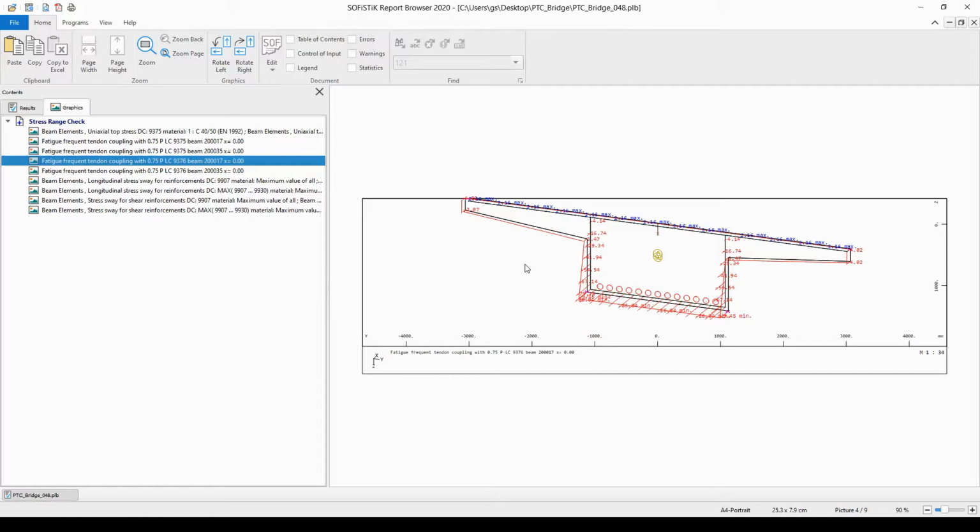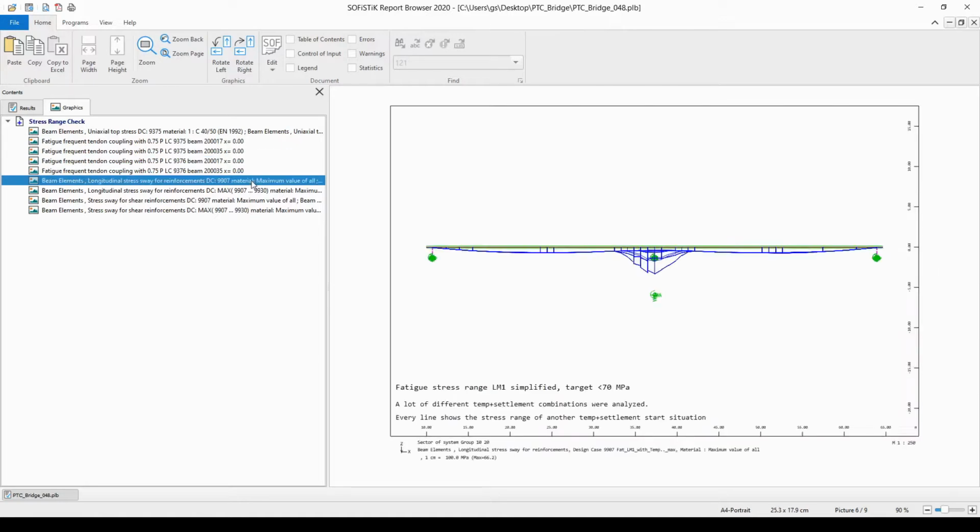could be a case, such as is presented in this picture, that although we have tension within the cross-section, it is located at the topmost fiber of the cross-section where there is no tendon or connection or joint of the tendon at all. And we might accept this situation since we can say that where the tendons and their joints are located, the cross-section is in compression. In the next picture we are going to overview the next check.